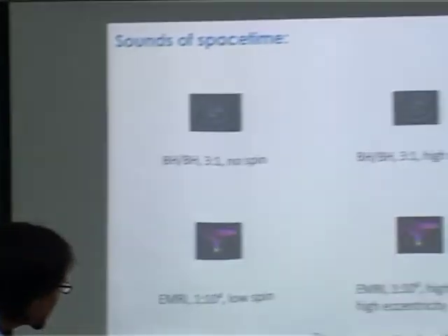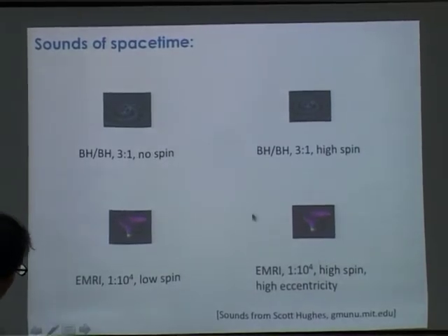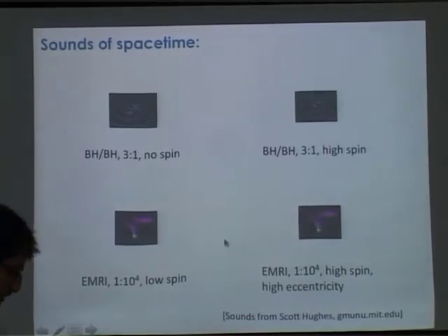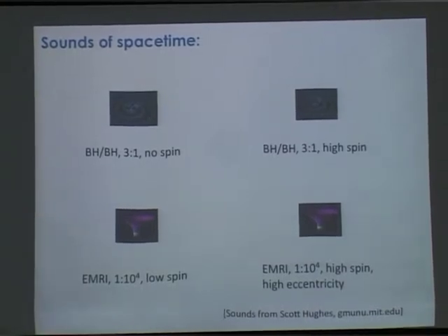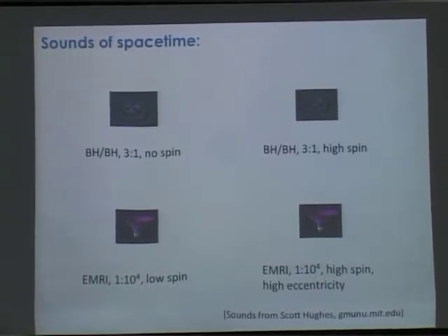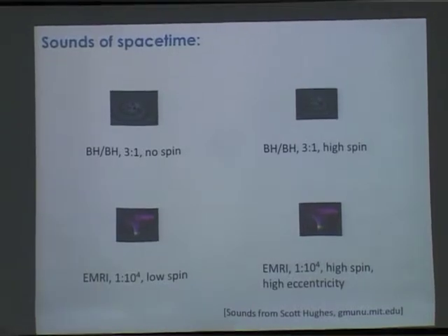Another one that's a little bit easier to hear is if you have eccentricity, for example. That also introduces additional features to the waveform, which you can, I think you can hear this knocking sound, this bump, bump, bump, bump, bump. And that's also going to increase with frequency and amplitude.